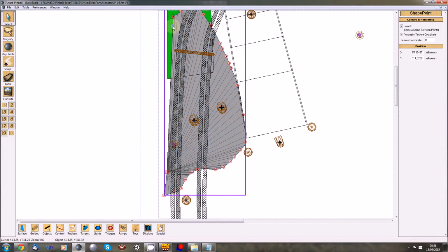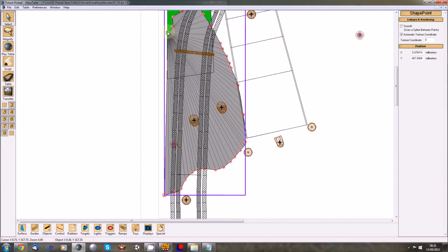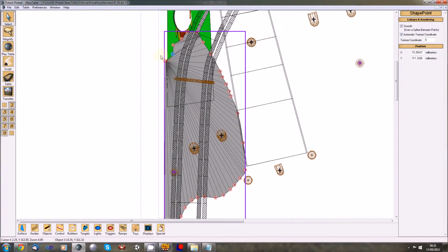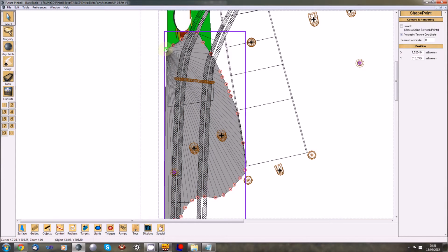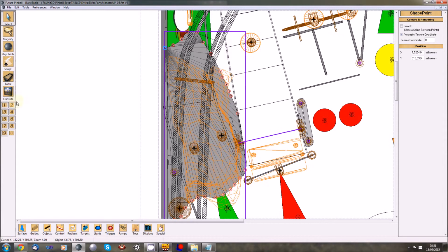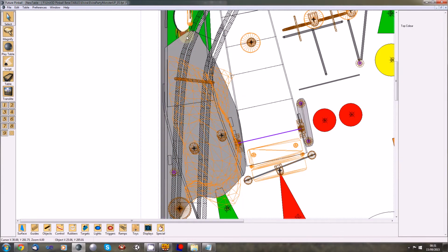And also, as I said in an earlier video, try to keep smooth points only when needed. Here it's not needed because it's a flat side, and it's not necessary to keep it. We can simplify this surface quite a lot.